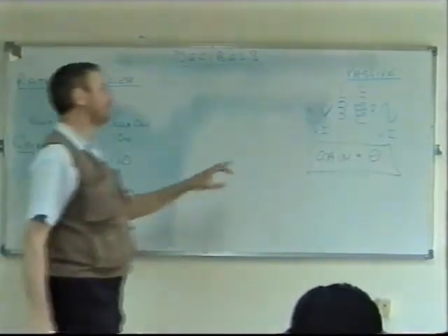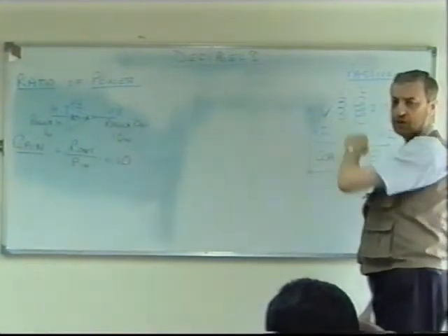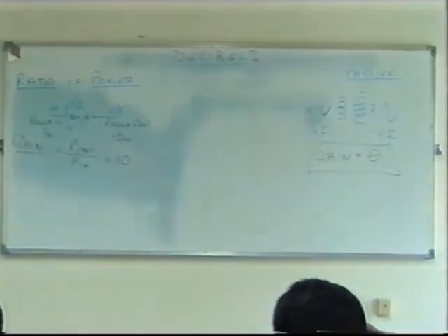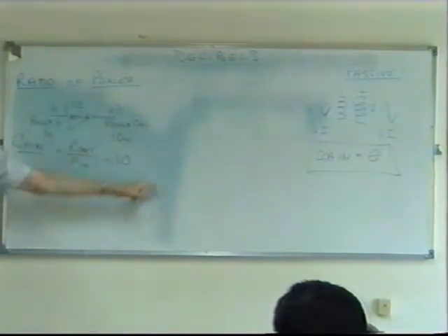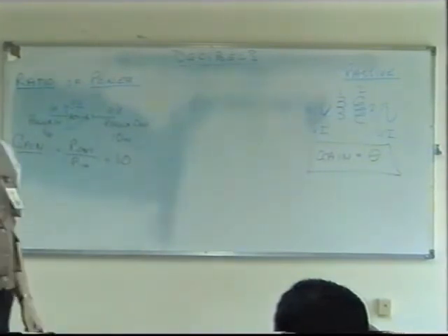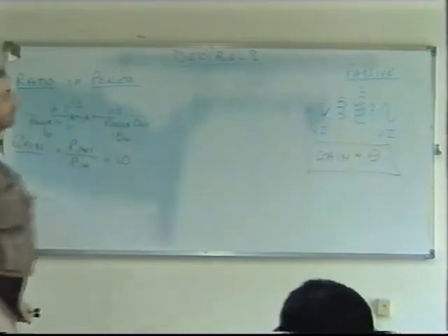So we cannot really talk about gain in a passive device. All we're doing here is changing the ratio of voltage to current. That's not an increase in power output. Okay, so we have an idea now about gain as ratio of power. And whenever we talk about gain, we should really be thinking of power ratios. Right. Okay. Now, once you understand that little point, and you've accepted that, now we're going to talk about logarithms.